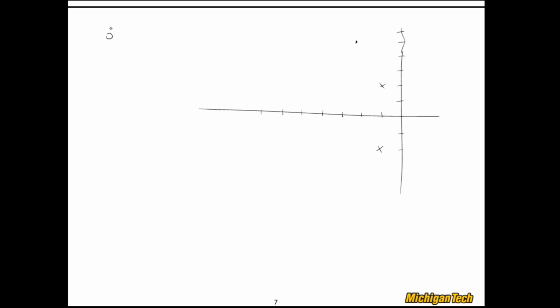One way that I can get this phase lead of 38.7 degrees is to stick the 0 of the compensator right there. The reason I'm doing that is just because it's easy, because that gives me 90 degrees of phase lead. And now I need to have a pole someplace such that this angle is 38.7 degrees. So what that means, let's see, let's define this as delta.